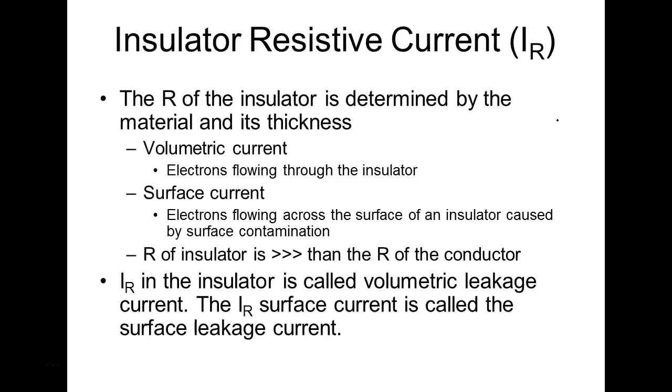So if your insulators get real dirty, it's going to change the capacitance of the insulator, and it's also going to change your surface current. It's not going to change your volumetric current, but it's going to change your surface current. You see this happen every once in a while with spark plugs. When spark plugs get really dirty, if you ever reach down and touch the spark plug wire, you get shocked.